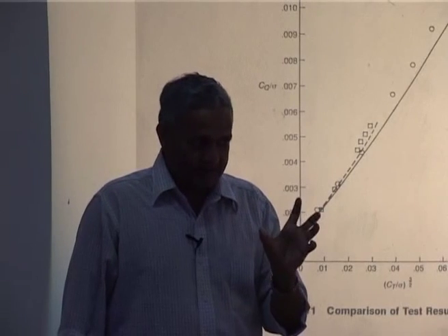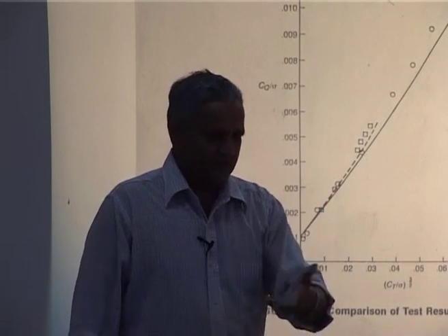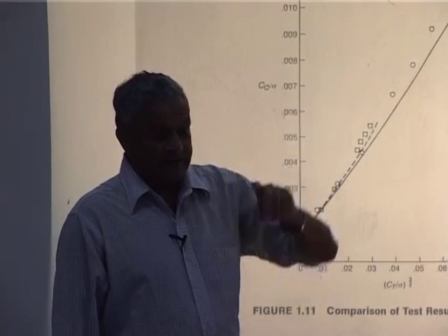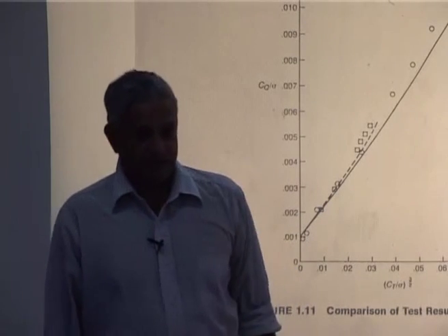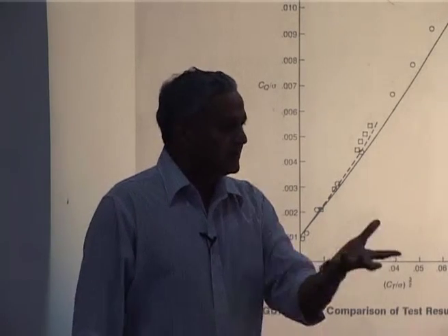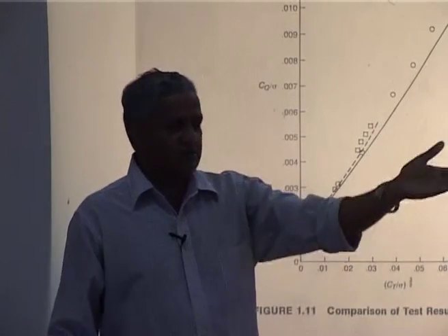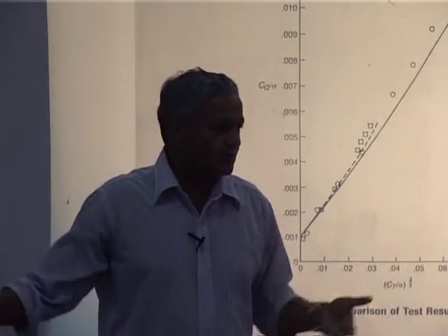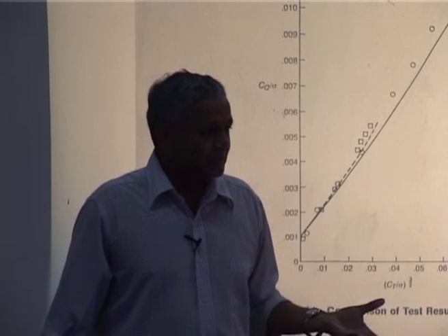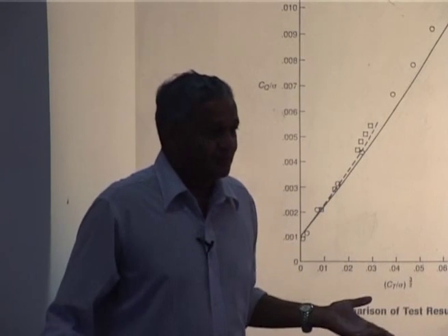But this factor in hover is related to stall. The same thing can happen in forward flight also. But if I simply represent Ct by sigma for a helicopter, Ct is fixed, because the weight is known, rho pi r square omega is known, sigma is known. That means Ct by sigma cannot vary for a helicopter.